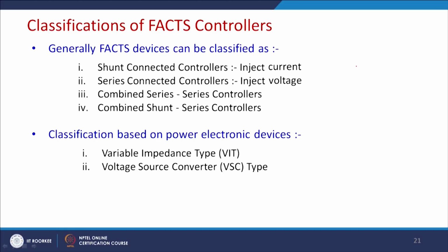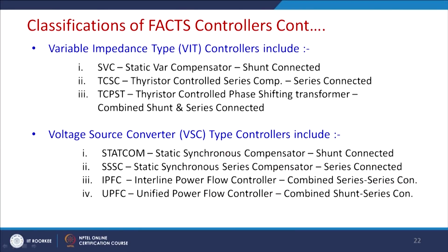So, classification can be done based on whether it is inserting impedance or a voltage source into the system. Now, these are a few nomenclatures which will be frequently used in our subsequent discussions. Students are required to note down and become familiar with these acronyms. This is basically the variable impedance type controller. So, it inserts impedance. SVC, the static VAR compensator, is a shunt connected device, and